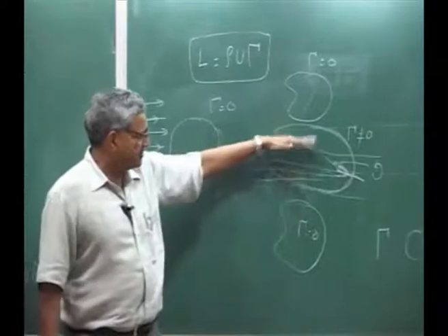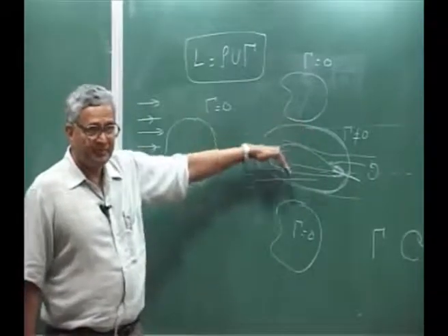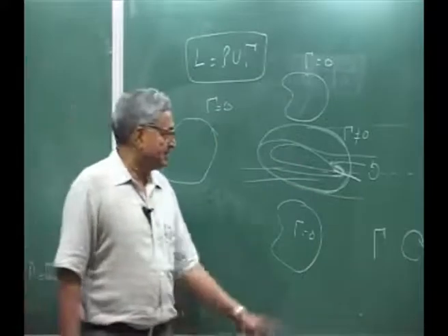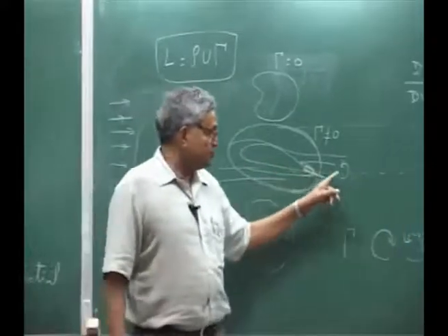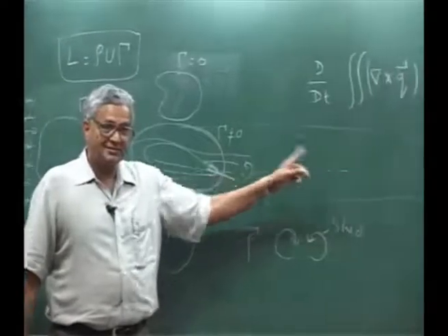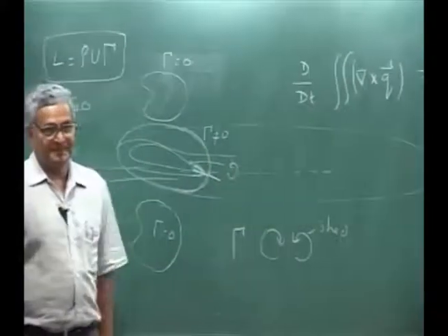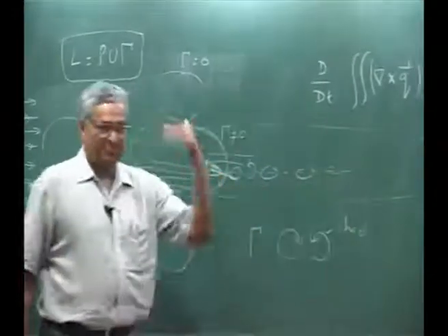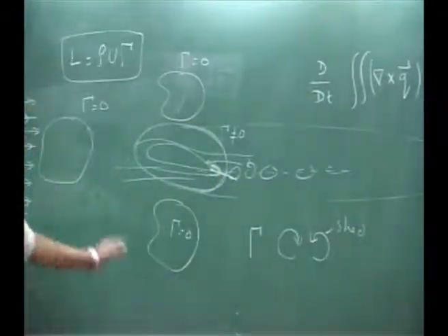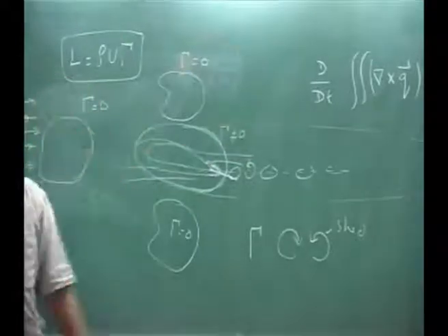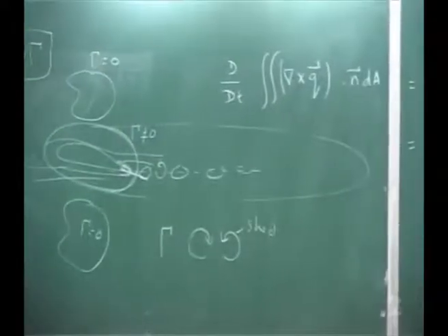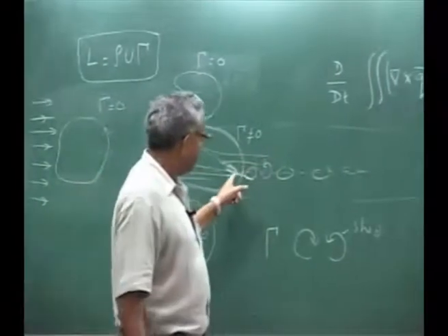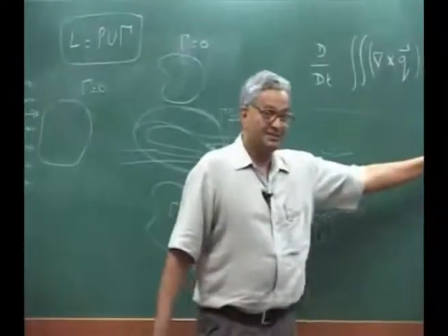But if it starts moving up and down, the aerofoil is oscillating, then what will happen is you will continue to shed vortices. You will have many. Okay. This is what the trailing vortex is. Now you cannot neglect them, because there is everything from the trailing edge to infinity.